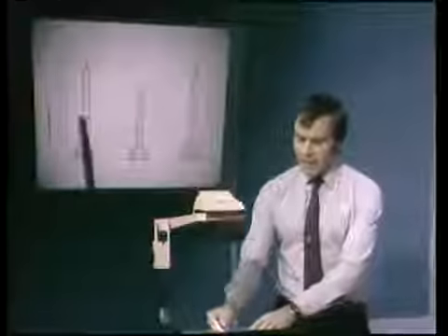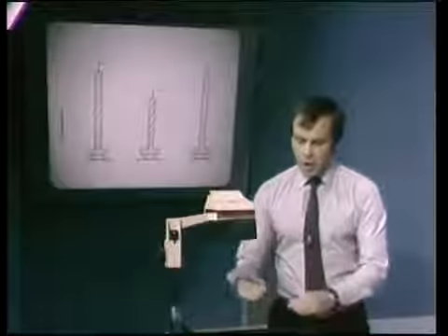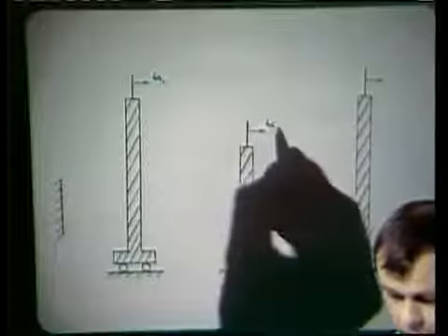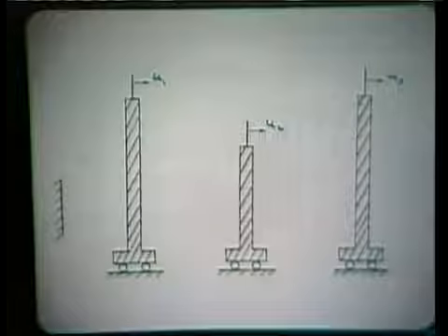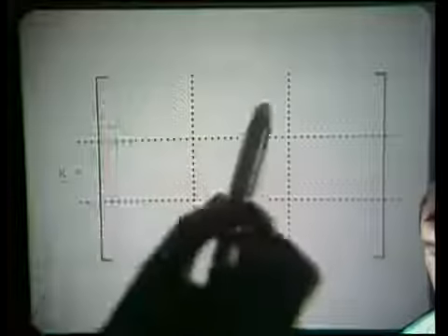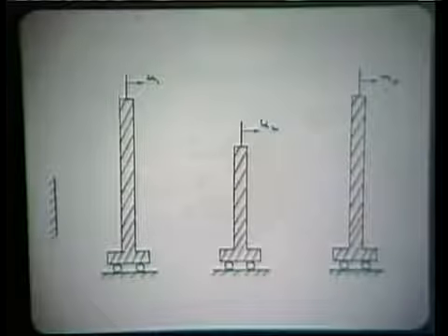Here I have drawn the carts without any springs. Of course, our degrees of freedom are here U1, U2, and U3, and the loads are R1, R2, R3. I don't need to put them in again. This system here corresponds to a K matrix with zeros everywhere. Blanks in these positions denote zeros. So this is a system that we are starting off with in this direct stiffness method: a system without any elements, a matrix without any elements also.